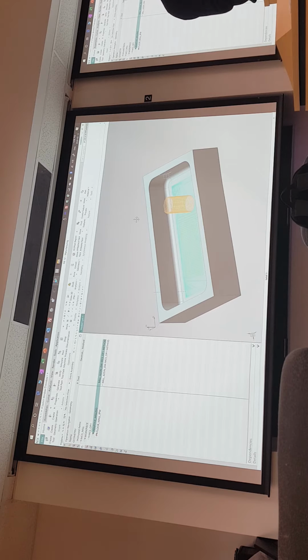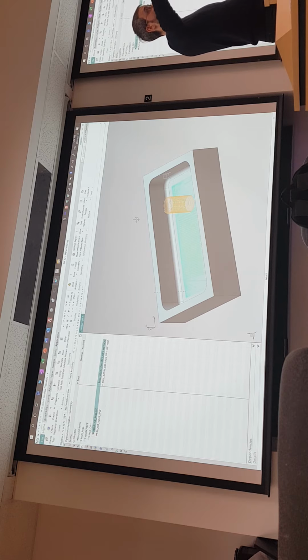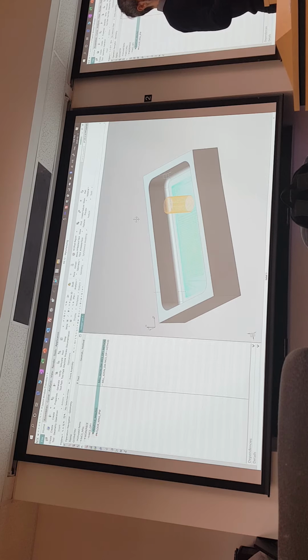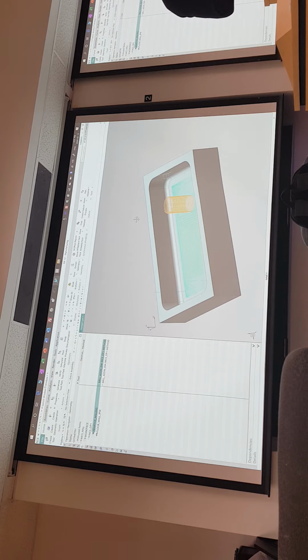And you'll find that when you go into specify your approach or your non-cutting moves, all ramp angles are set at 15 degrees. Please change that to 3 degrees. Don't use 15 degrees. It's way too much for these types of cutters. Usually cutters can do anything from 1 to 5 degrees. That's a good range to use, and then maybe 3 degrees is a good conservative number.